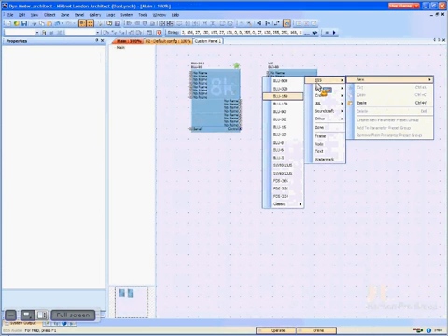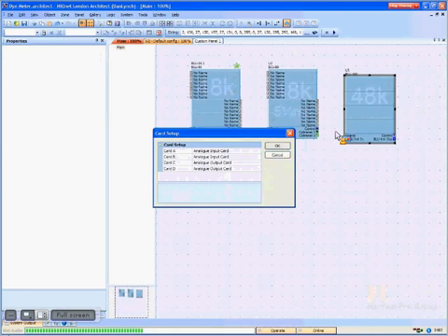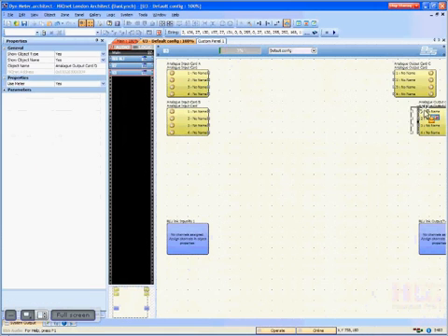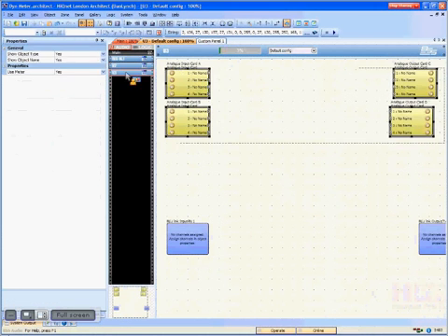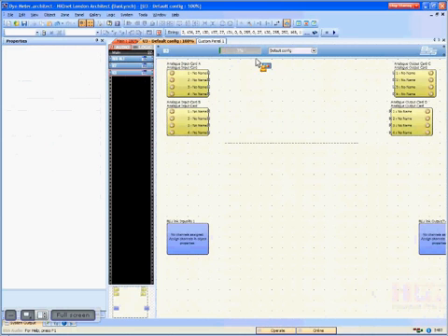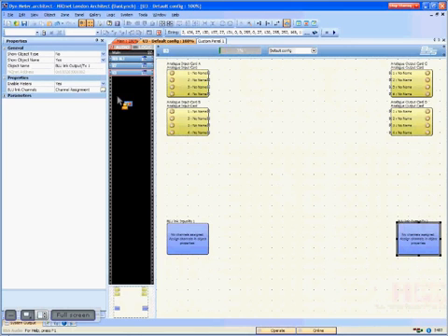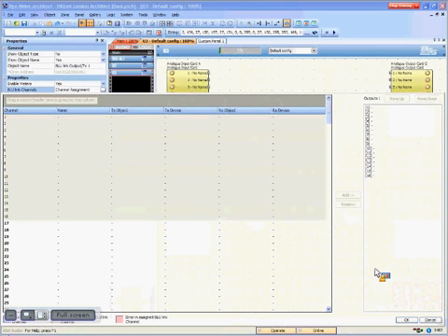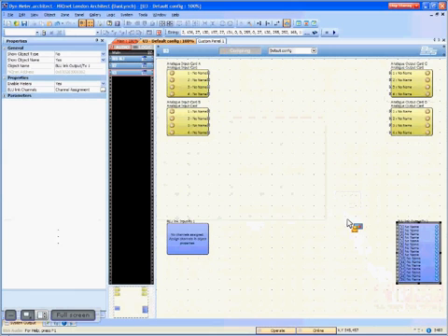I go to a Blue 160. Turn the meters off. Meters off. These meters off. I'm at 3%. That 3% is reserved DSP for BlueLink. I set up this BlueLink node to use 16 channels. The 3% jumps to 9%.